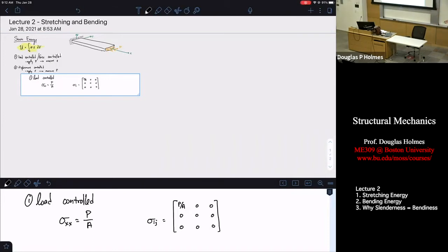Now, it's probably been a while since some of you have seen mechanics of materials, or perhaps your memory of it is a little bit foggy, but I'm sure someone is thinking, wait a minute, I remember that there's some sort of Poisson effect, and if I pull on this thing in the x direction, I hope you can see this at home, it starts to shrink in the other directions. So pulling on this in one direction, I've only applied force in one direction. It causes displacements in all 3. It causes it to stretch in x and shrink in y and shrink in z.